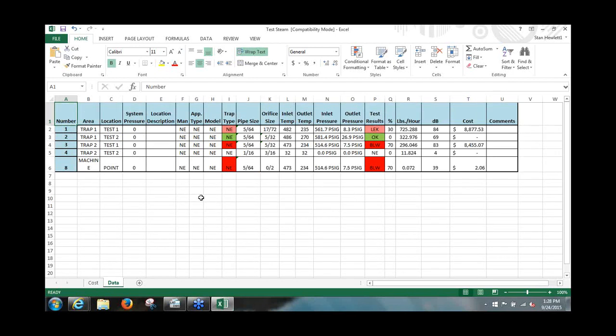So we're going to be looking at this one right here, these 2 traps actually, because they're costing the most money. Actually, probably about 99% of the cost right there. So we're going to flag those 2 traps and replace them at the end of the season so that we're not losing more money next year. Okay. Now, is there any questions concerning this report?